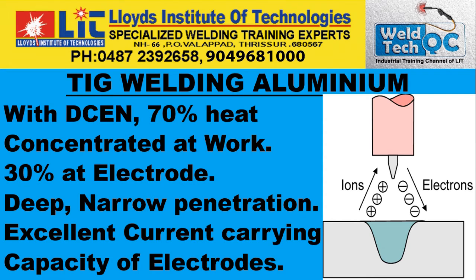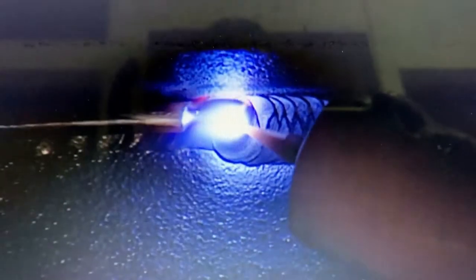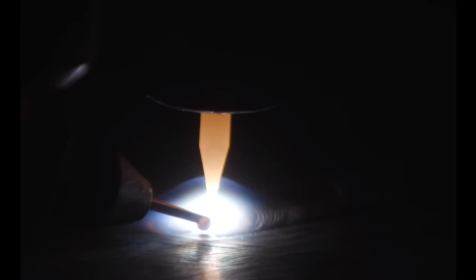Let us see what happens with DCEN, that is straight polarity. Here, on the contrary, 70% of the heat is concentrated at the work, whereas with DCEP, 70% of the heat was concentrated at the electrode. Okay, here it is vice versa. It is 70% heat concentrated at work and 30% at the electrode.